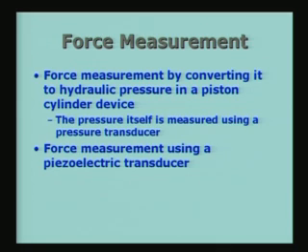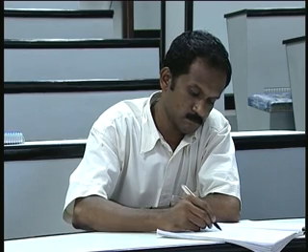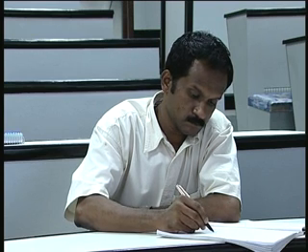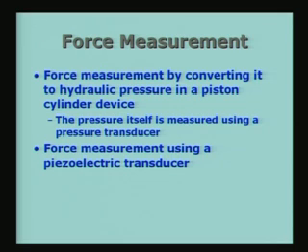In fact, we have already seen different types of pressure transducers and we know how to use them. So, a pressure transducer can be used for measurement of force by converting the force, instead of to a displacement as in the earlier case, to a pressure. It can also be measured by using what is called a piezoelectric transducer directly. We will look at it a little later in more detail.